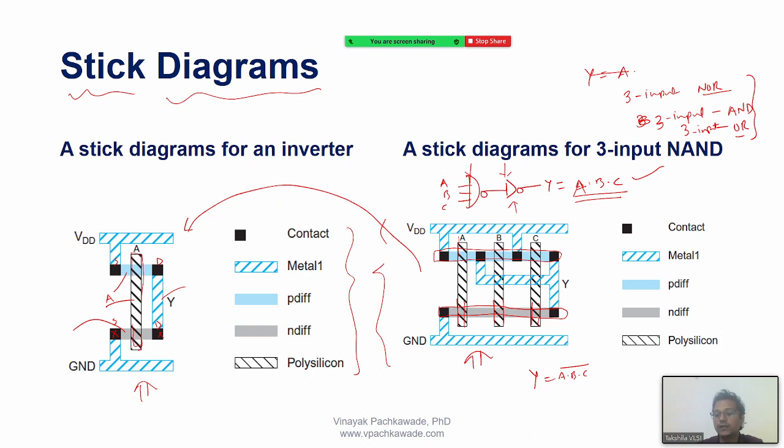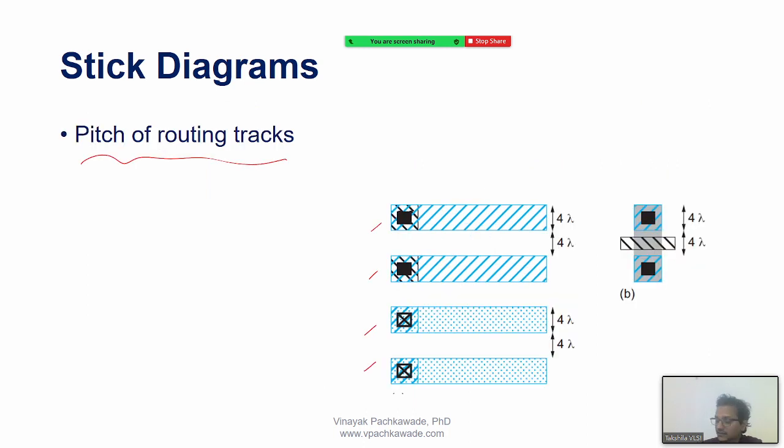So you know how many metal layers, how many layers are there. Accordingly, you can just create a layout, physical layout for any cell. And these are some rules again. So what I see here, yes, any question? No. So 4 lambda, it seems the metal width, there is a spacing between that I must follow. If I violate, I will run the DRC. What is the difference between these two? Okay, this is just the width of individual metal, and there is the spacing.